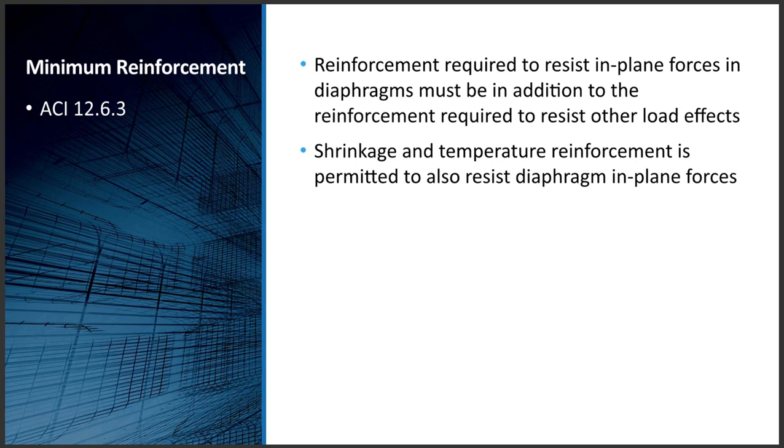Now, there are cases where, depending on the location of where the diaphragm reinforcement has to go, the flexural reinforcement in the slab is not highly loaded. That's when you can take advantage of the bars that are already in the slab for other purposes than the diaphragm forces. We're not going to illustrate that here today. We're going to do it the more traditional way of providing separate reinforcement for everything. But there can be situations where you can utilize your slab reinforcement as part of your diaphragm reinforcement, provided, and this is a big provided, that the stresses in those bars are very, very small.